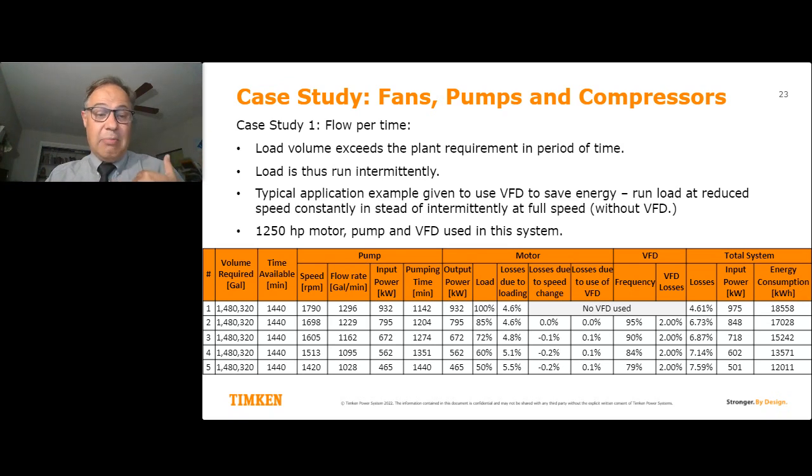And if I do the time calculation and multiply my time with my energy consumption, I will see that I have a significant real life cost saving. This is energy that I have not consumed, but I have achieved the same result. I've pumped the same amount of fluid. Now, I can run through that iteration, and I did it all the way down to where we want it to be, our 50% loading.